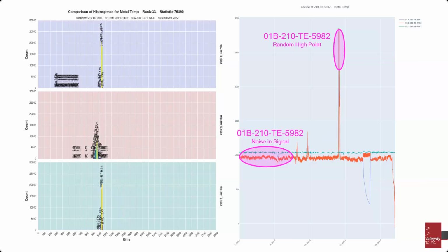There's one case study I believe coming up where there's a throttling valve on an attemperator, and it's something they know they have to do regular maintenance on. Having those differentials monitored versus time, they can see when they start needing to do a rebuild on that valve.